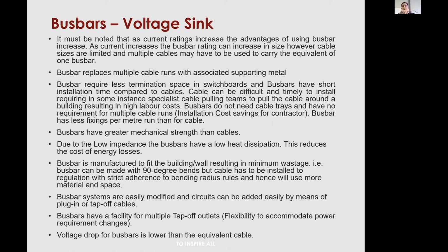That I've outlined all in this slide, all the various gains from using a good solid bus bar. The point I should make is that if you have a one inverter, one battery system, you of course do not need a bus bar. The bolt connection between the BMS, the fuse holder and the inverter is fine and good enough, and that is the lowest number of connections that you can make, and therefore is the desired design.